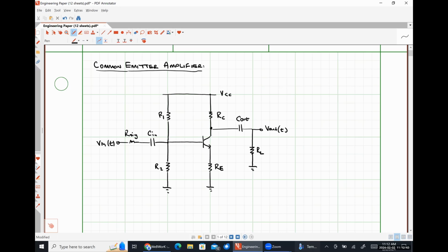The reason why we have to use capacitive coupling is because if we didn't have these capacitors here, this resistor, RL, would appear as if it was in parallel with the resistor RC. And so it will actually influence our gain. Not having this capacitor right here means that if this signal is very small, our input signal looks like ground. This guy right here looks like ground. And so it's going to pull our base emitter voltage to something close to ground, and it's going to turn that transistor off, which means it's not going to work as an amplifier because it'll be in the cutoff mode or very, very deep in saturation mode, since VCE would be so much larger than VBE.